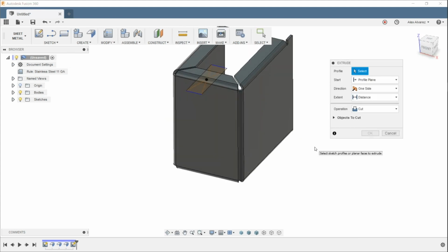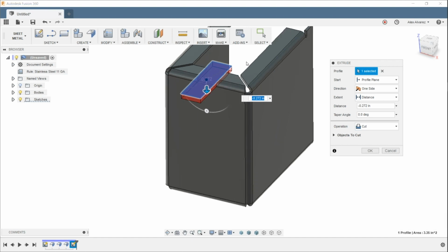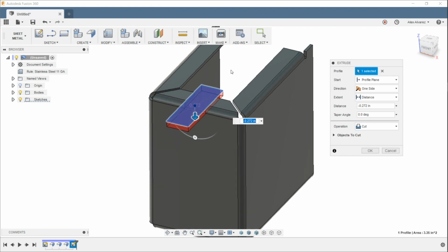And then using my modeling commands, E for extrude, and give it some sort of cut depth, right? Now, typically when you're working with sheet metal, especially if you're coming into or from Inventor, notice that if you're working with the sheet metal cut, it usually defaults to the thickness, right? So the thickness of the material is the kind of cut that you're going to be working with. So if we try to type thickness, take a look at what happens, right? So it turns red. It's saying that, hey, that parameter doesn't exist. Go ahead and change that value, right?